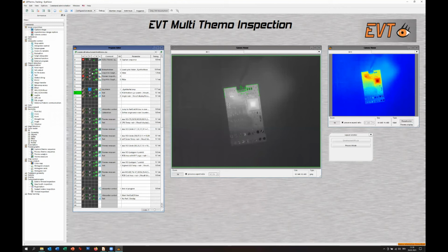So we have the text file, the log file. Invert means you can invert the result column. Each tool generates a result. So capture image says good, meaning we got an image. But if you say, even if it's bad, I want to have a good result, you can invert it. Or you say, I don't care about the result. You simply click on it and you disable it. So we have these now.